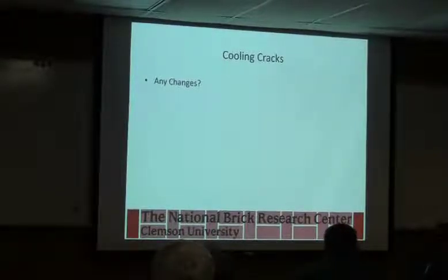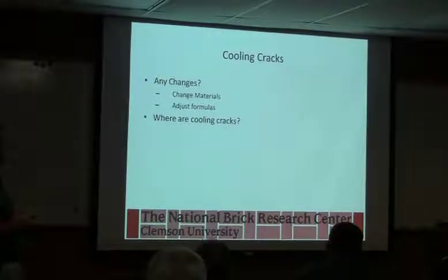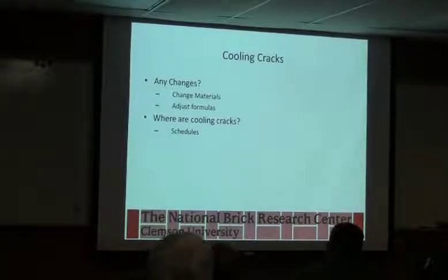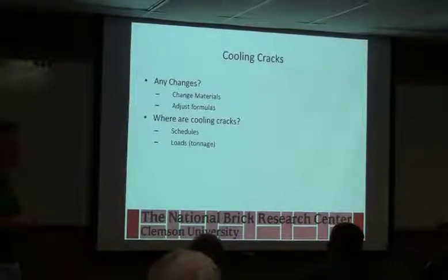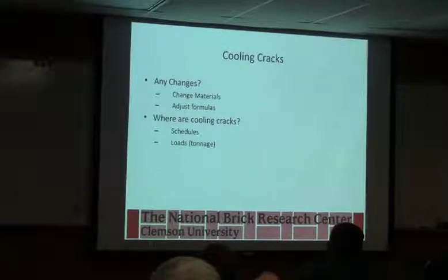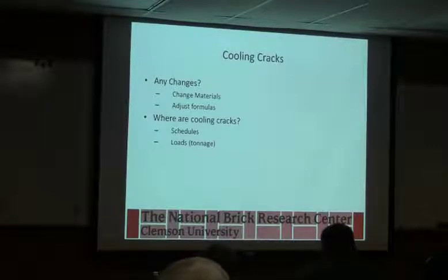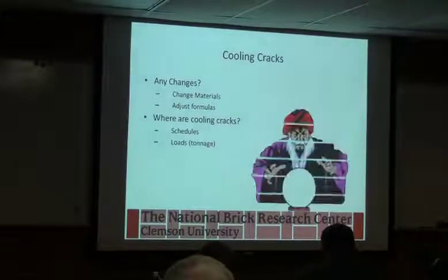Cooling cracks. Any changes? Changes in materials, adjusting formulas. Where are the cooling cracks? Look at your schedule to see if something has changed with that. How much load do you have on it? Is it actually a mechanical issue that's causing the cracks, that's not allowing the brick to cool uniformly, or are there loads on it that are overloading certain areas?